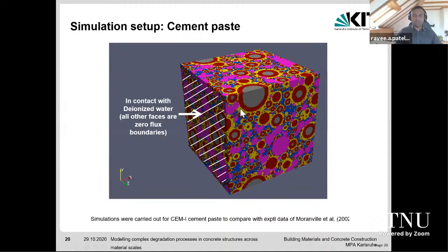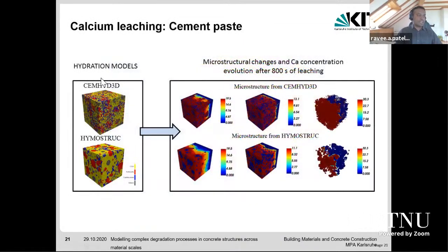So you can see here we have two representations. One is the nanoporosity, which evolves like a continuum scale simulation, but you need a relationship between porosity and diffusivity, and then a pore-scale simulation, which explicitly represents a pore structure. So from this simulation, I can know how the nanoporosity is evolving and how the microporosity is also evolving because of the dissolution of these bulk phases like Portlandite. So these are example sets of simulations.